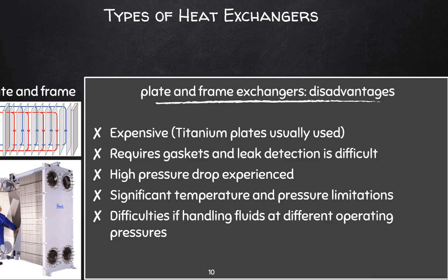even though a wide range of plate materials can be used, such as stainless steel, copper. Typically titanium is used because of its strength, and you need to pick a material. Stainless steel is not very good as a material because the thermal conductivity is not that great. A pure metal like titanium will be much better.